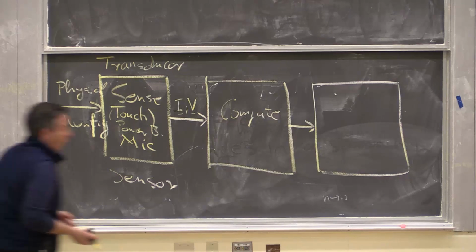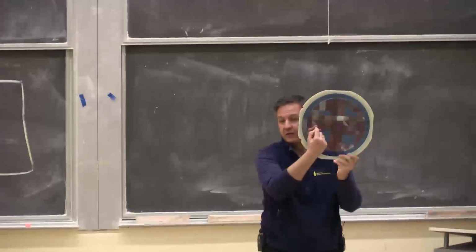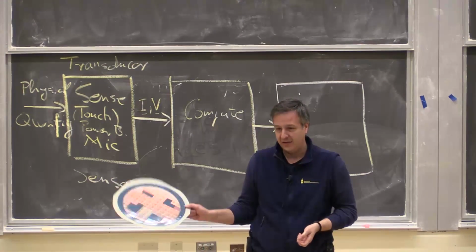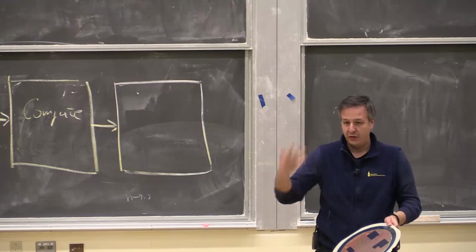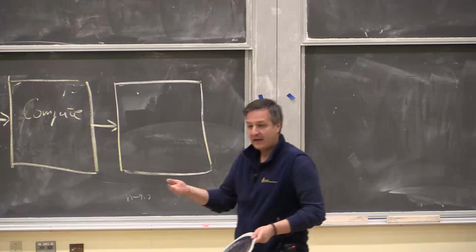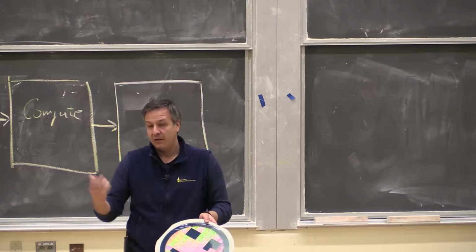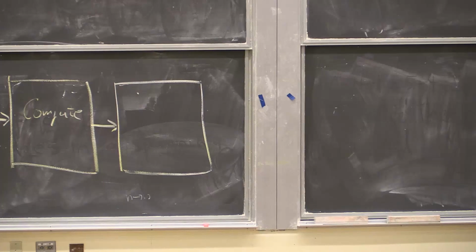While I'm describing this, for the people who came today, I'll hand you this. This is a 300 millimeter wafer from a state-of-the-art foundry of integrated circuits. If you look at your pocket, all your devices, you sum them up, you maybe have this much silicon. Silicon is the most abundant element in the Earth's crust. So how do you make smartness from rocks? That's what humankind is really good at. You make it just like you print newspapers: photomasks. You expose, you lay the material, you then remove it, and like a cake, you build up a whole stack. It doesn't look like a whole stack, it's very thin. The stack is only about 10 micron thin on top of a couple hundred micron of base silicon. I'll hand this around so you can take a look.